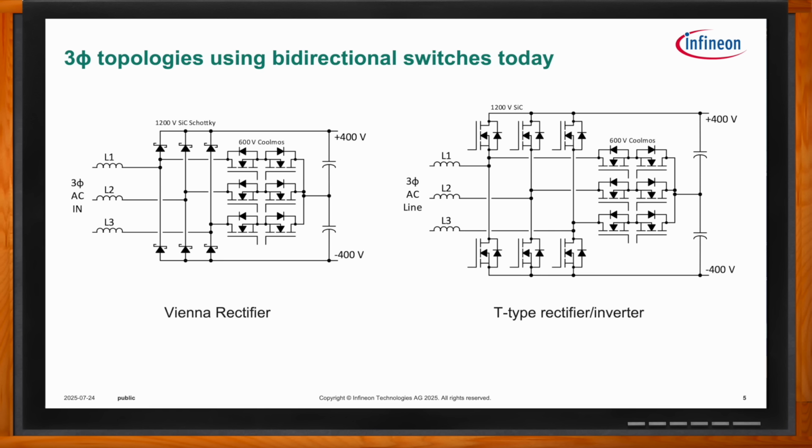The difference here is going to be that with either single phase or split phase, you have 100% ripple, meaning that there are periods where the power flow goes to zero every time you have a zero crossing. When you have a three-phase system, you never have that condition. You only have small, like 12 or 15% ripple, and all three phases are contributing power at all times. So that's one of the reasons why at these higher power levels in data centers, they now prefer to use the three-phase input.